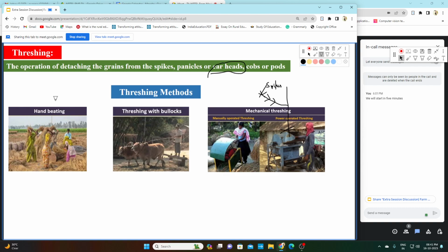The structure of planter and seed drill is almost the same, the only difference is in the metering mechanism. In the seed drill we are generally using a fluted roller or bulk seed metering mechanism, and in the planter we are using a single seed metering mechanism like the inclined plate planter. So two operations are over. The third operation has two parts.